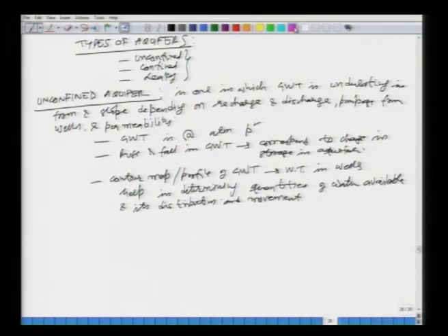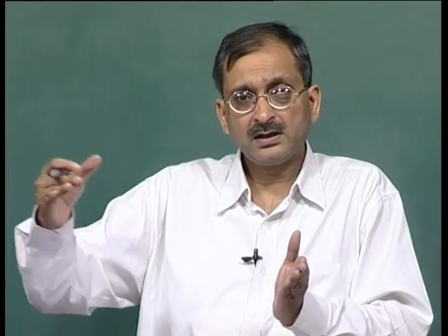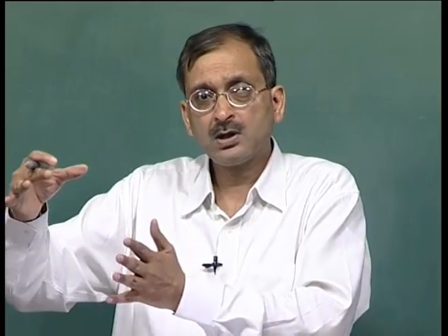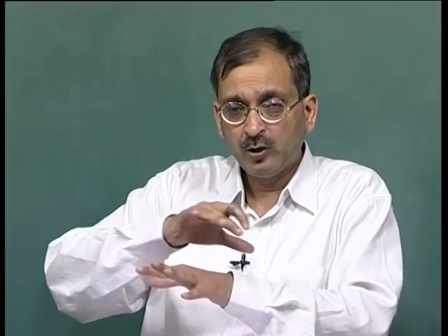Once we do this exercise, that contour map is very useful in determining the quantities of water available, because it tells us how much water is available in a certain area, its distribution, where it is concentrated, and how it can move. Let us say you have developed a contour map with a certain contour interval, 1 meter here, 2 meters here, and so on. If the contour lines are very close together in one area, it means it is steeply sloping down, so the movement will be much faster there. If you have very flat gradients, that is where you want to tap the water.